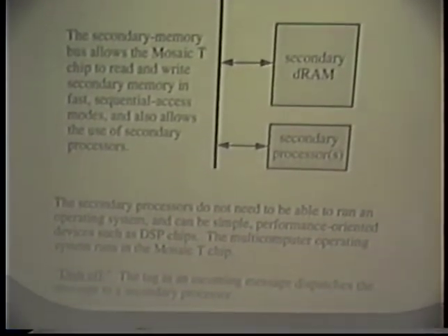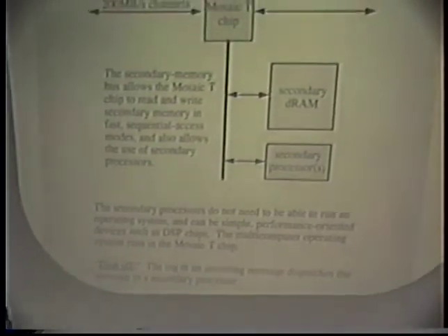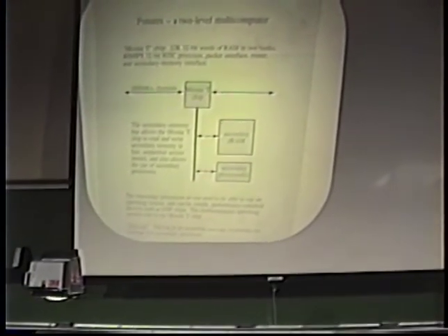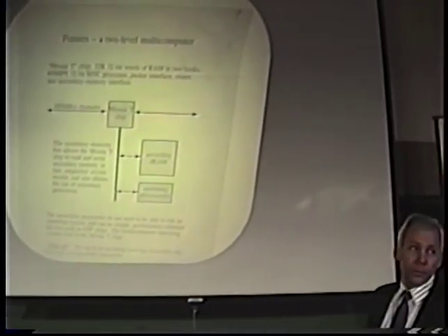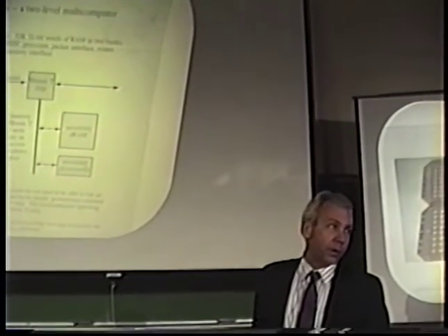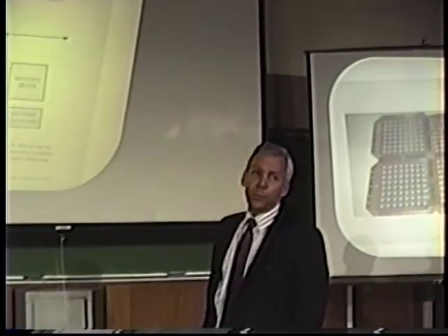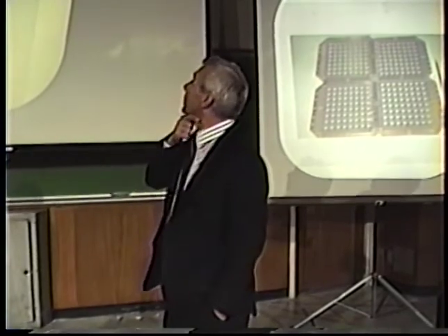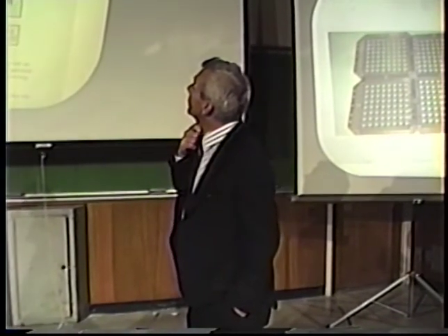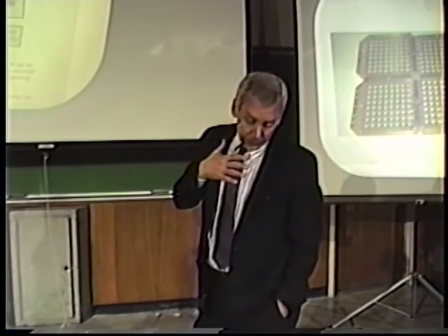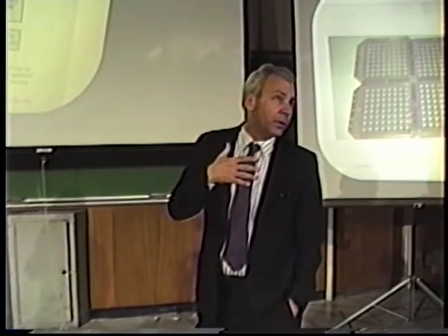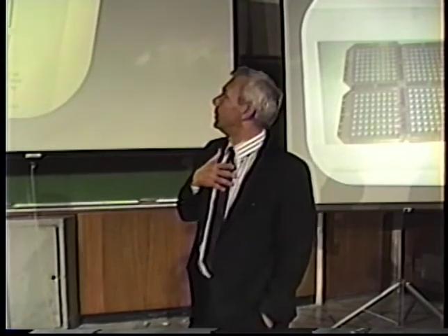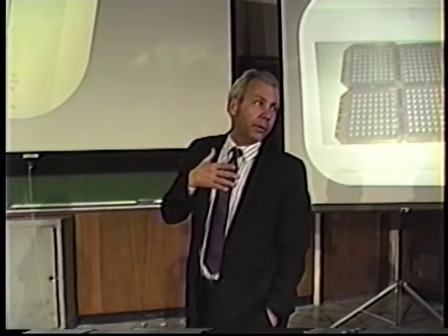This is a machine that is a lot like the Mosaic C, except that we've learned how to design better processors in the meantime. And this is targeted for a somewhat smaller feature size technology, 3.3 volt operation, still about a ½ watt per chip. We've also seen the desirability of increasing the memory bandwidth on the chip, simply because we've been able to push the communication bandwidth.